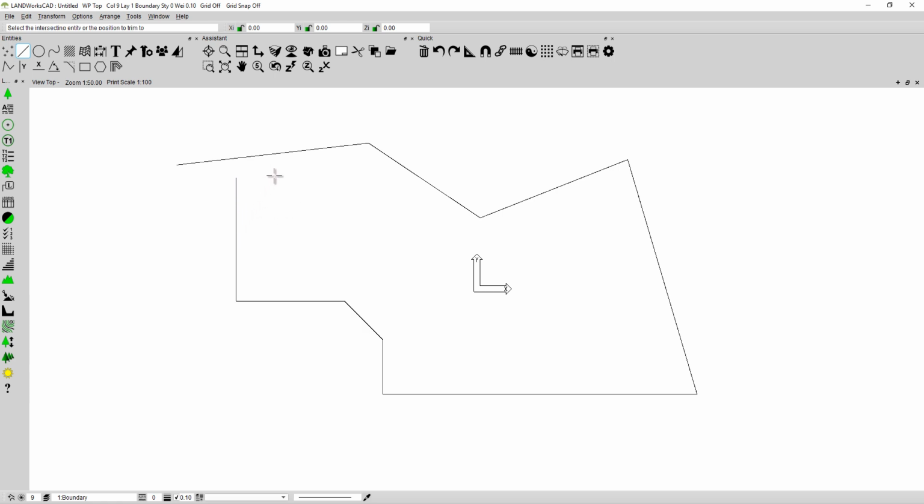Again, select this line. I could now trim till it met this line. So it found where this line and this line intersected. I could do exactly the same for any other line. I could, for instance, say lengthen or trim, same command, this line until it lines up with this line. So this line has an imaginary go on forever-ness about it.